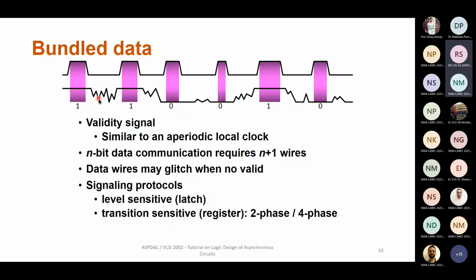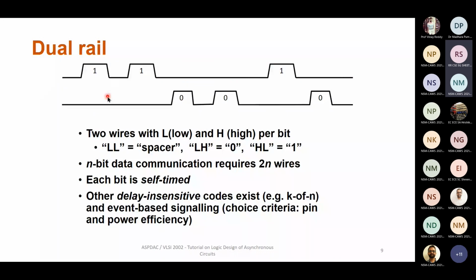Whereas in the previous slide, when I talked about dual rail, it is a self-timed system. So in a self-timed system, if my adder has completed its job early, then the done signal can be generated early and my processor can actually run faster. Am I making sense here? Is it clear what is going on?